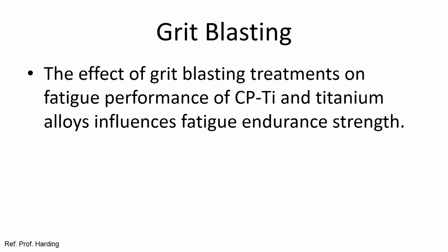It's been found that grit blasting of titanium implants, be they commercially pure or alloyed implants with aluminium in them, influences the fatigue endurance strength of our implants. This is very important when looking at the sustainability of our implants in function.